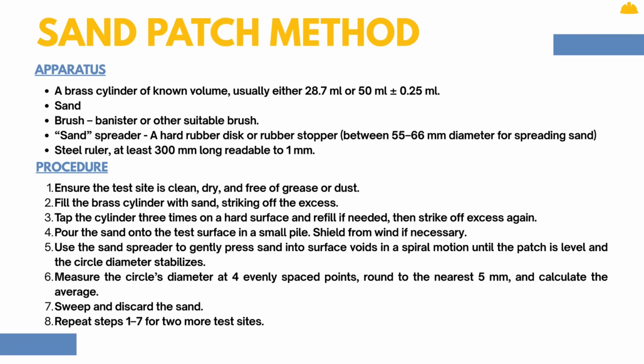Next, the sand patch method. The apparatus needed are a brass cylinder, sand brush, sand spreader, and a steel ruler. Start by making sure the test area is clean, dry, and free from dust, grease, or debris.